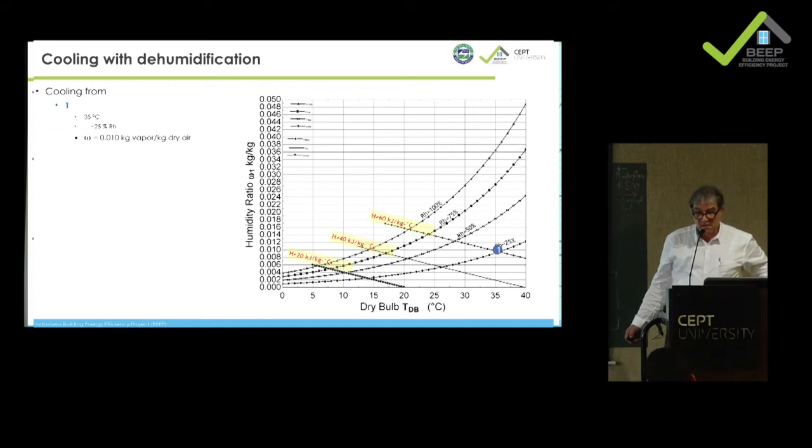Yeah, exactly. And now when you switch over to evaporative cooling, you're not changing the heat, but you're changing the water content. You are not changing the total heat. That means the heat of the air goes down and the heat of the vapor goes up. It's a kind of balance. It's adiabatic. That means there is no exchange of heat with the outside, let's say, of this volume of air and water. And the law tells us that in such a condition, it will always follow the enthalpy line. Exactly.